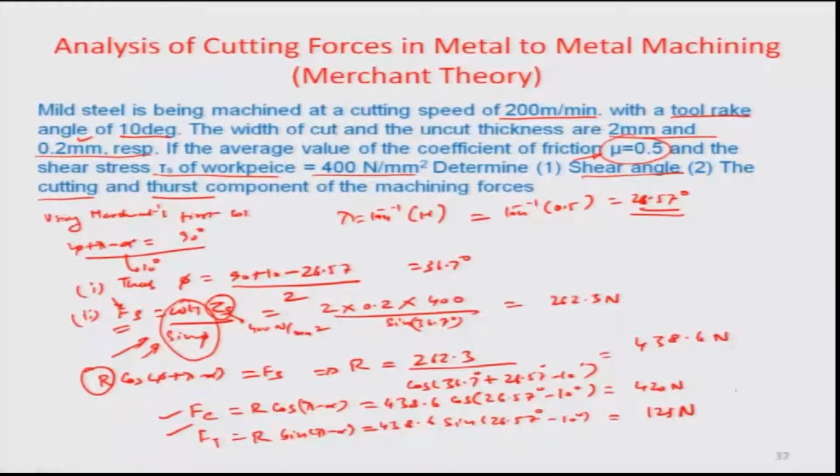So in a nutshell, you can now estimate from the material properties and the geometrical properties the normal forces and the cutting forces in the tooling zone or the cutting zone. In the earlier example, we had done the reverse, looking at the measured cutting and tangential forces to find the ultimate shear strength. Having said that, I think we have covered more or less everything that is needed to understand Merchant theory properly.